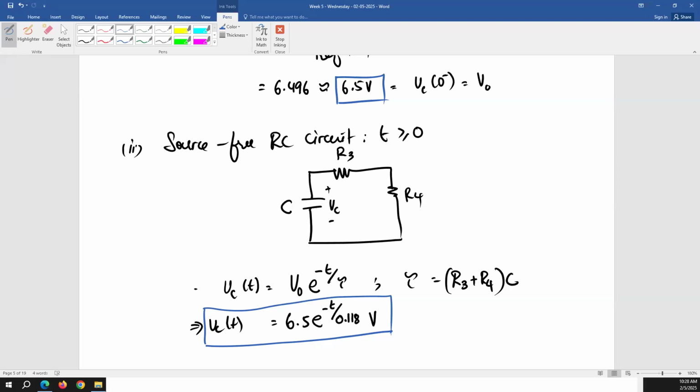And when you put a capacitor, you're creating a filter, basically this RC circuit. Let's say the capacitor is charged to the maximum value, and then it starts discharging. But this RC time constant you keep quite large, such that when the next cycle arrives, the capacitor has not discharged much. And then it will start discharging again. So basically, this pulse is going to become something like this.